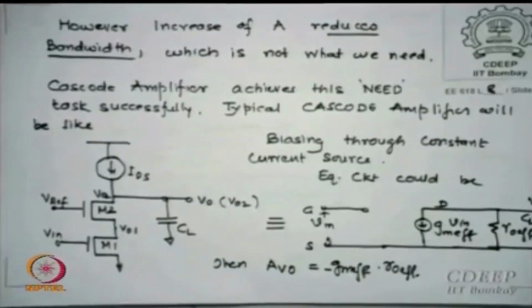All that I have done by this technique is to improve the current source which normal voltage to current converters have. Relatively RO is not very bad even there, 10 to the power 6 or so, but how much do I want for a good current source? Infinite. So by boosting this, I am trying to get a better current source out of the amplifier.